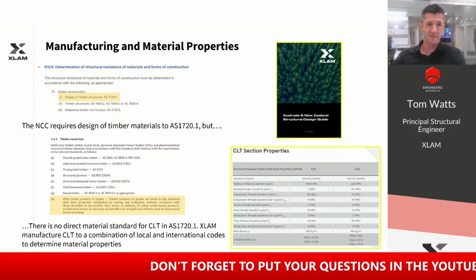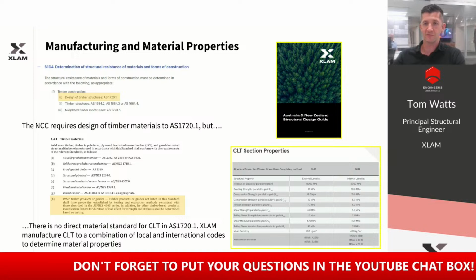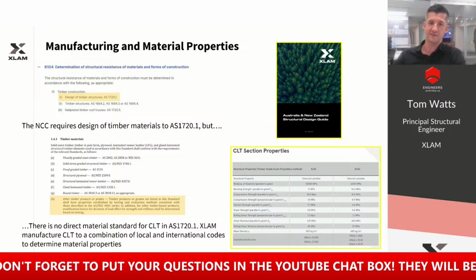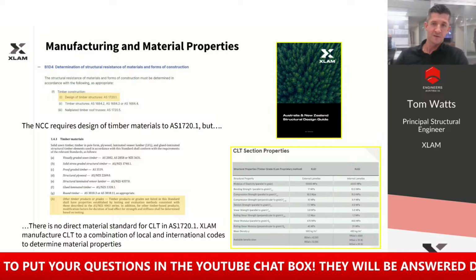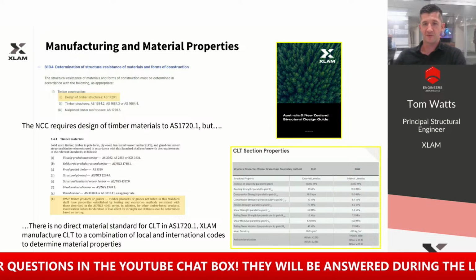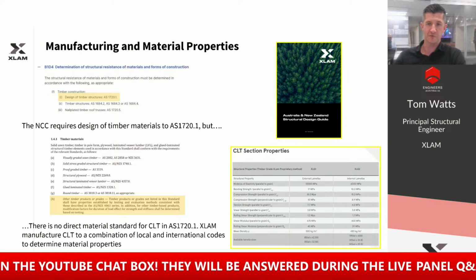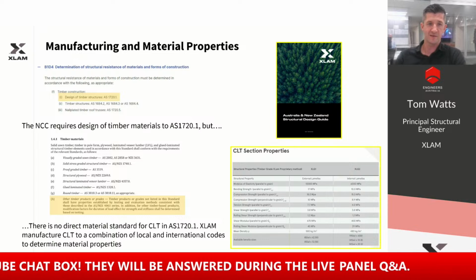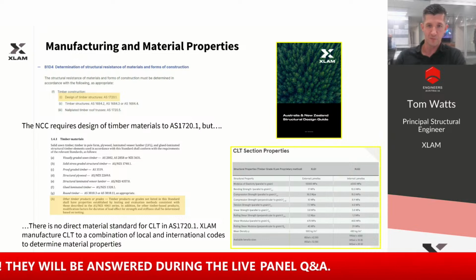And at this point in time, it's, I guess, key to note that there's no reference for CLT included within AS 1720 Part 1. However, there's the option to comply under the other timber products and grades, which is in heading H under clause 1.3.1.